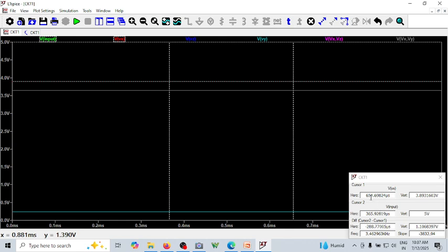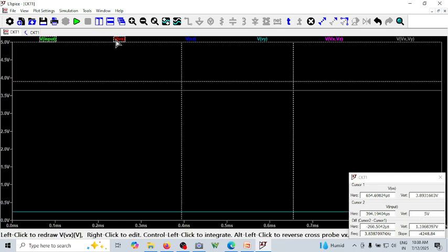And what does this indicate? This indicates at what time you are measuring. So this corresponds to 653 microsecond here, and this corresponds to 365 microsecond. You can see the moment I change this, only the x-axis is changing. There is no change in the y-axis at all for this particular cursor, because this is your second cursor. When I'm moving this, just have a look at this second cursor and only this horizontal line remains there, no? So that's why there's no change.